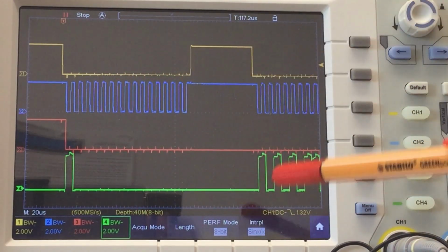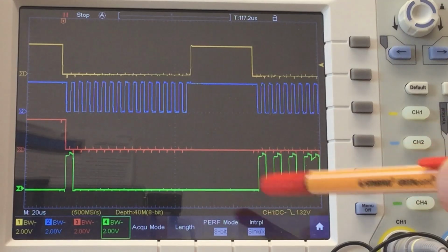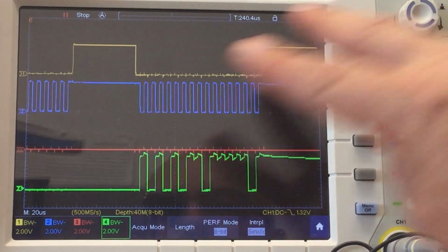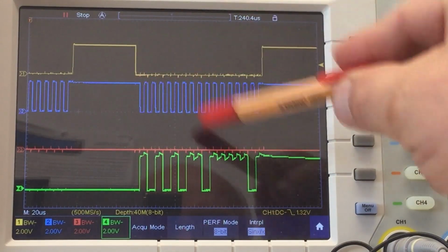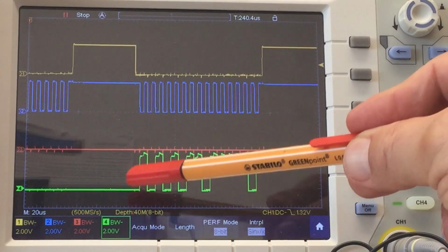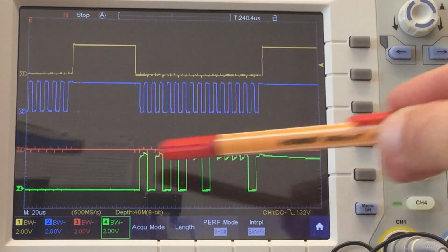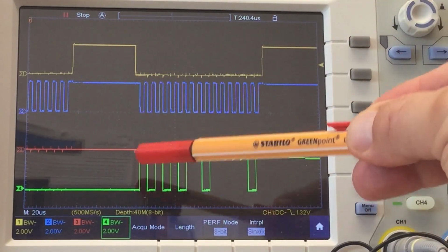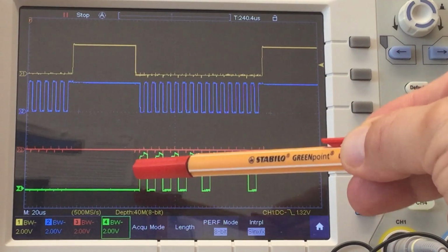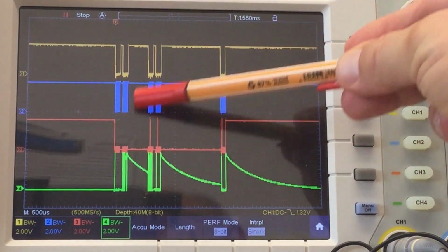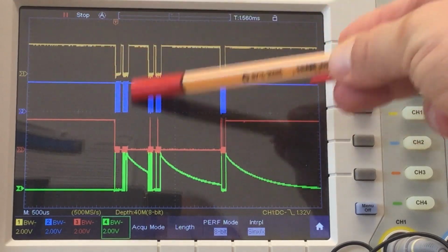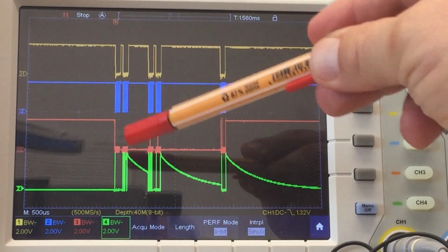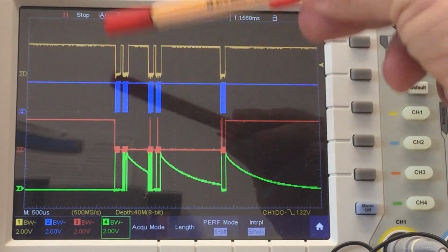The first bit, the most significant bit in any transaction, any 16-bit word you get back from the chip. And then I try to read the data that comes back, the angle in the second SPI transaction. We are still in the 2 transactions for the read register. And the error bit is still set, and I get some angle information, but I disregard that because I have a general error warning. So we were just looking at the first 2 SPI transactions that basically do a read register. In this case, all 0, so read angle register.